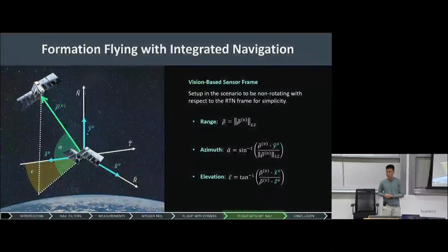There has also been interest in SLAB to do integrated navigation, so fusion of carrier phase differential GNSS with range measurements. This could come from the crosslink, or this could come from a dedicated device like a laser rangefinder. It could also be from camera models where we use azimuth and elevation. So this is angles-only navigation, analogous to the Starlink mission, which I think Justin will be sharing with you in the subsequent week or two.